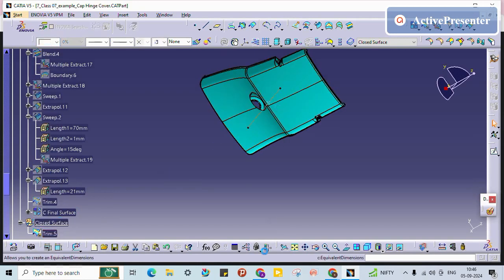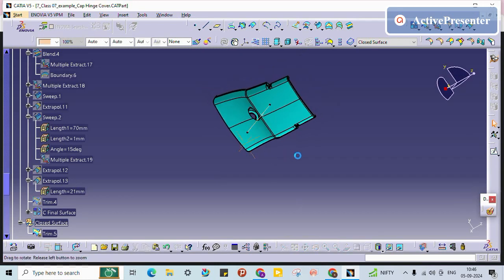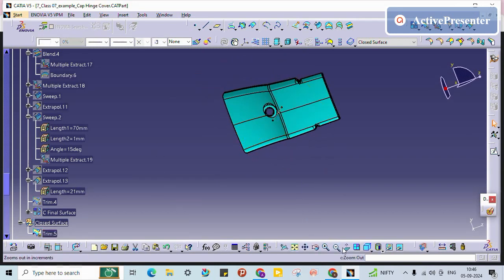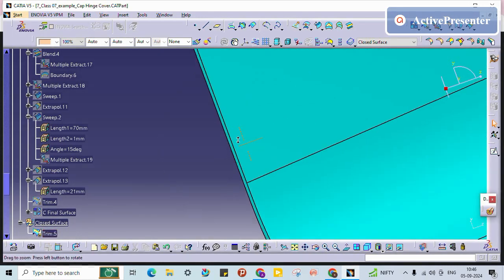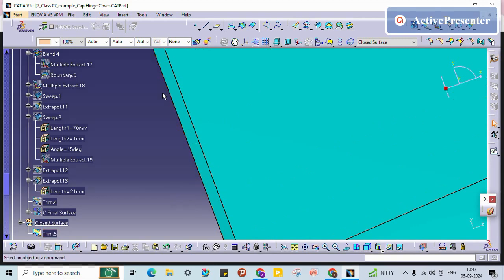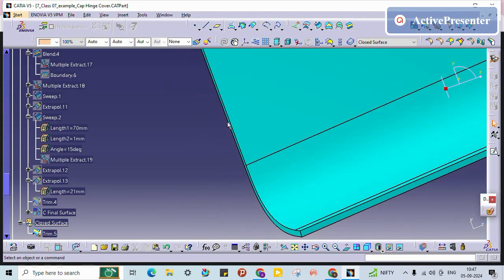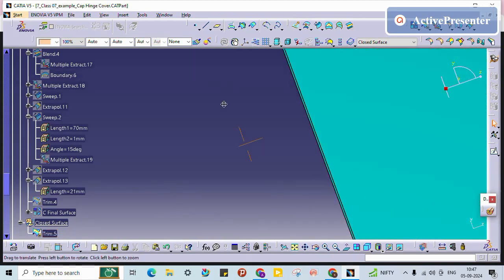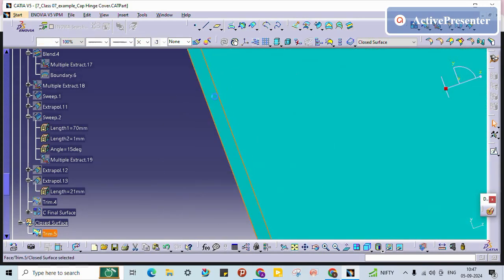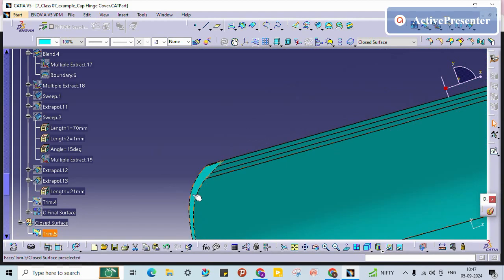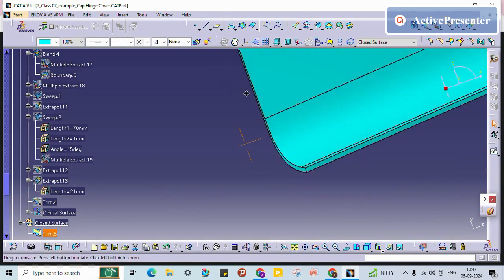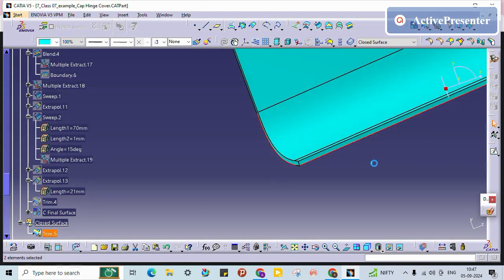So with respect to this tooling direction, see, now the A surface is visible, so it won't have any undercut. So in tooling, you need to consider this one now. This draft maybe it is less, you can increase also. Our intention is to keep all the surface to be visible. See, your part will come like this and it will be in this side, if you see, it will be easy. So this is what your parting line.